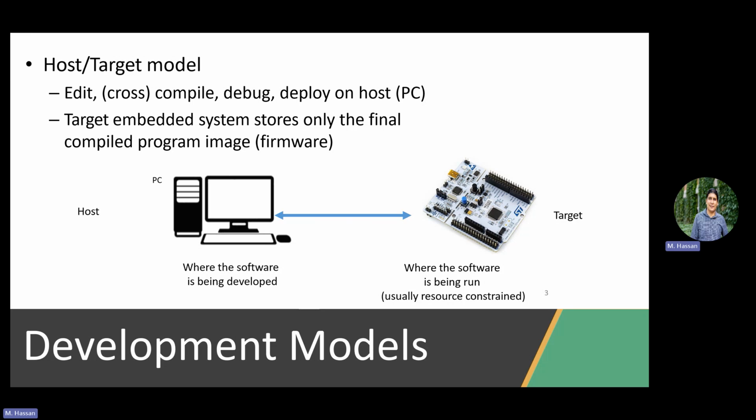It does not allow you to run a GUI IDE where you can simulate stuff, look into the result and then burn it there. It will only take the bare metal application binary and execute it for you. So you need something that you can play around with, try different things, simulate, and target different embedded platforms. Once you are done testing and development, you just go and burn it there. We call this the host-target model for programming. You are using a host for development that is different from your eventual target.